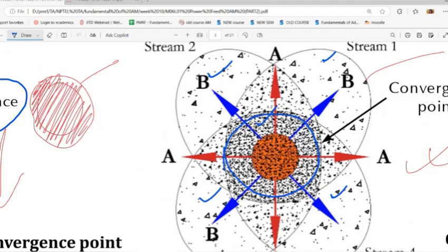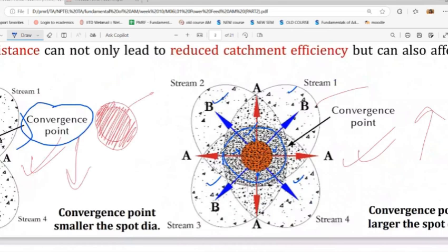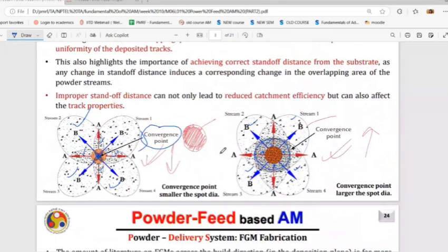Some of it will also come into the deposition because of denudation as well. That's why my deposition rate will increase, meaning more powder particles will actually participate in the deposition process. So my deposition weight, if I measure the weight after the deposition, will be higher.